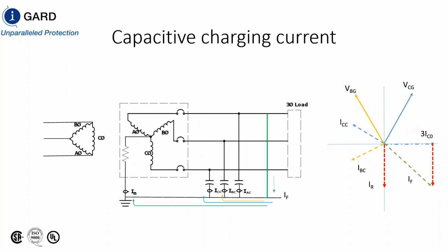When you have a fault on the system, and here's our fault right here, we faulted A phase. So we have three paths of current for the three fault paths for the current to take back to the source. We have a path of current going through this method, a path of current going through this method, and a path going through the resistor.